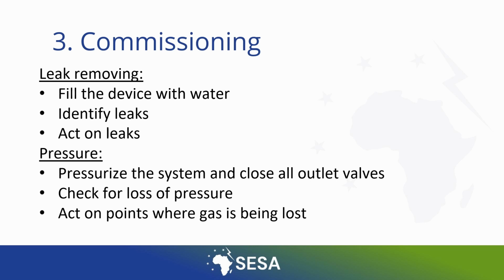In the same way, it's necessary to do a technical test. This means checking that there are no points where the system loses gas. It is necessary to carry out this action to avoid losing a quantity of gas that must be used for cooking. First, the entire system is pressurized with a digester full of water with the help of a compressor until a pressure rise is observed on the digester manometer. A tire inflator, a compressor, is enough to do this.